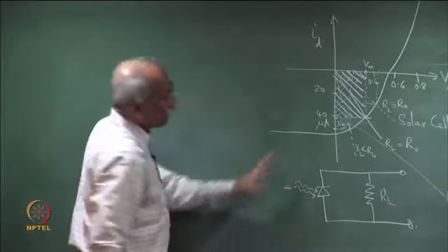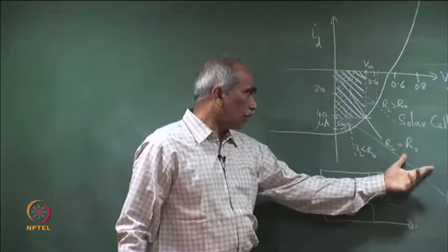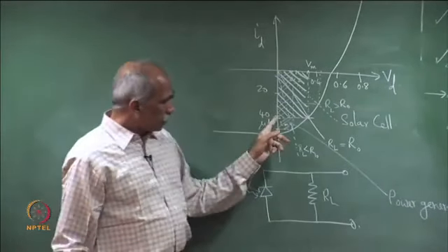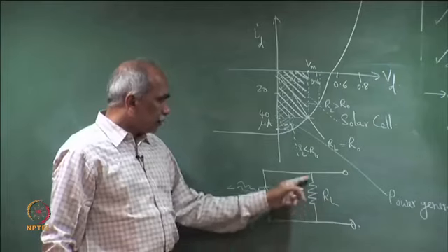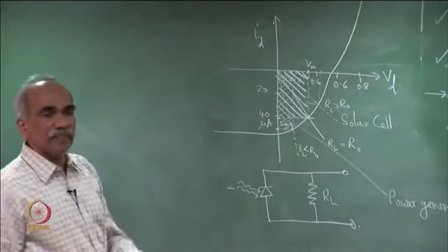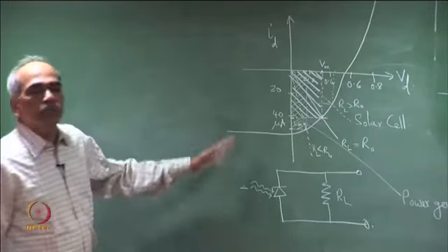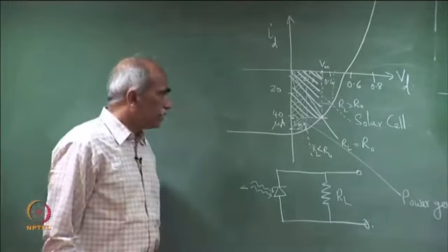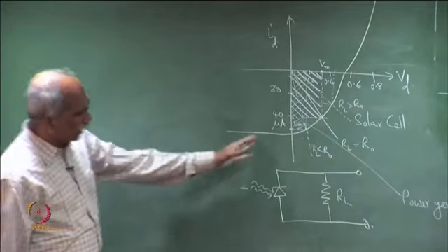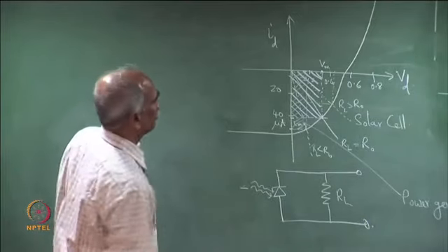So, a solar cell is basically a photodiode which is operated in the fourth quadrant and without any bias. An important issue is the choice of the load resistance from a circuit designer's point of view. The materials issues are completely different. So, this is from a circuit designer's point of view, to get maximum power out of this.